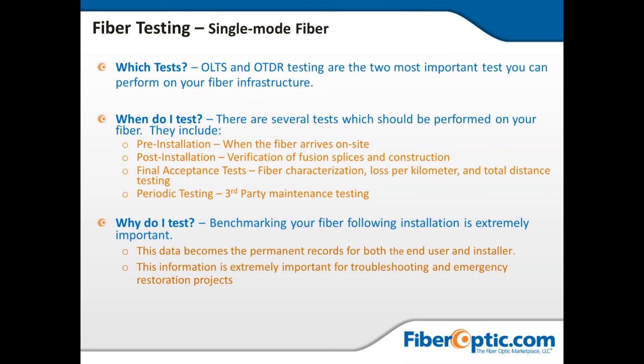Now keep in mind the spikes of a back reflection on a mated connector pair on an OTDR will give you the number for it. So if the back reflection, the height of the spike, is, and I'll pick one out, negative 30 dBm. Well, that's a typical PC or flat connector from the old days. And if I am buying much more expensive ultras and I'm not getting negative 50, then either the connector's wrong, somebody's going to go out and probably clean it, but maybe change it out, or maybe substituted connectors on the install that shouldn't be there. And it's going to be a real big deal. And that's the final.